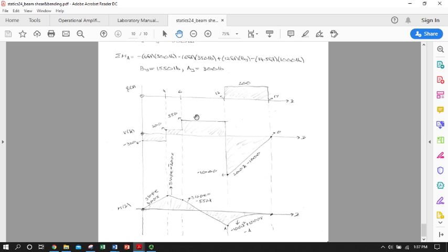So these are all polynomials, so I can basically take the integral of this function kind of graphically, knowing that this is a constant. So the integral of a constant of negative 300 is going to be some line with a slope of 300x. 300, so it's 300x, and I know that the moment is 0 at the hinge support, so it starts at 0. So this line equation is actually just 300x, and it goes up to this point, and then it's not going to take a step function because I didn't apply a point moment, I applied a point load.